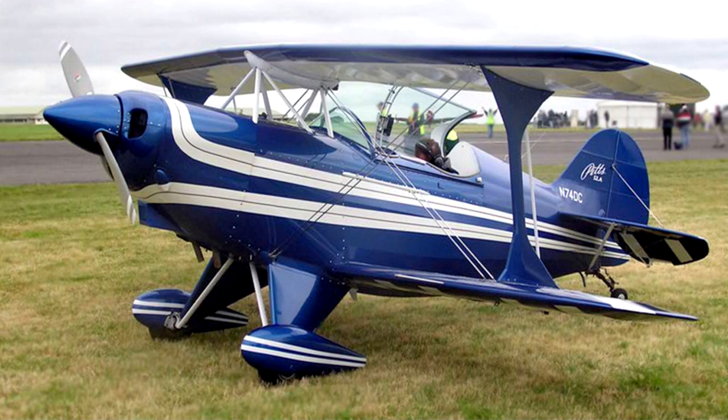Very few biplanes fly at more than 200 knots in level flight, so the air loads are low, which means that a truss-type design, which is covered in fabric, is satisfactory. The wing spars, interplane struts, and bracing wires form a lattice girder of great rigidity, which is highly resistant to bending and twisting. Unfortunately, this system also generates a relatively large amount of drag, which accounts for the fact that biplanes fly relatively slowly.